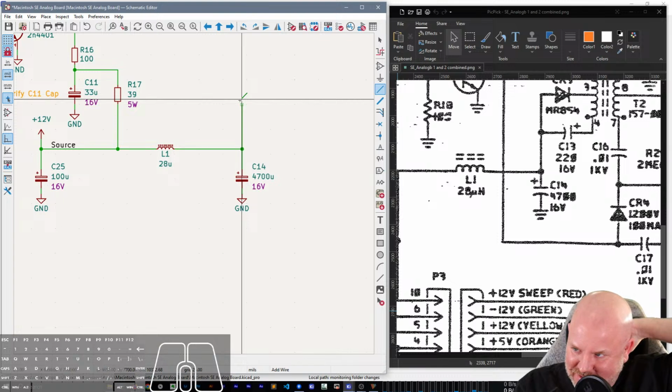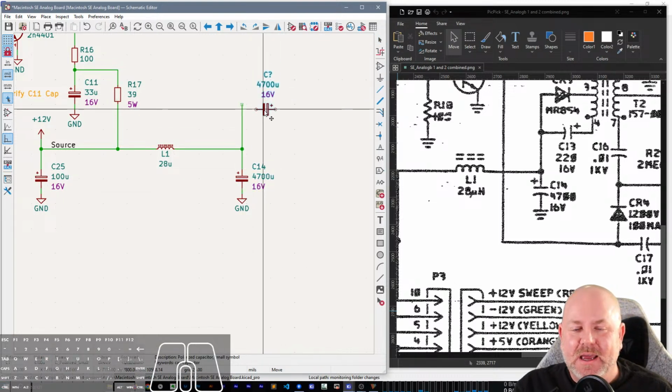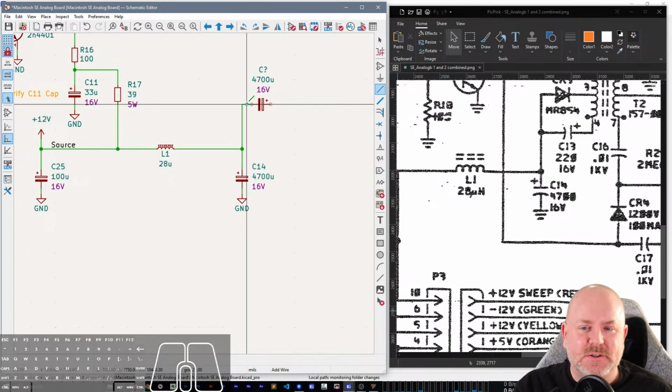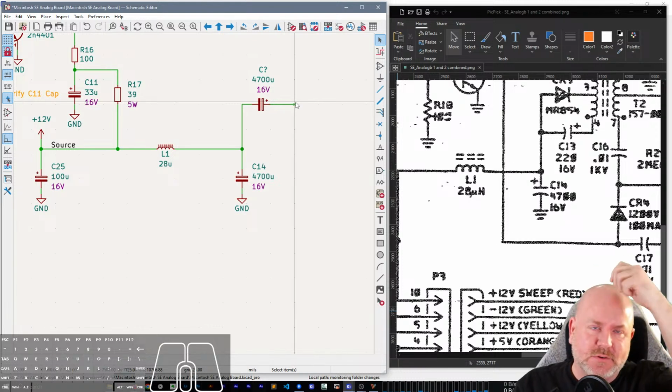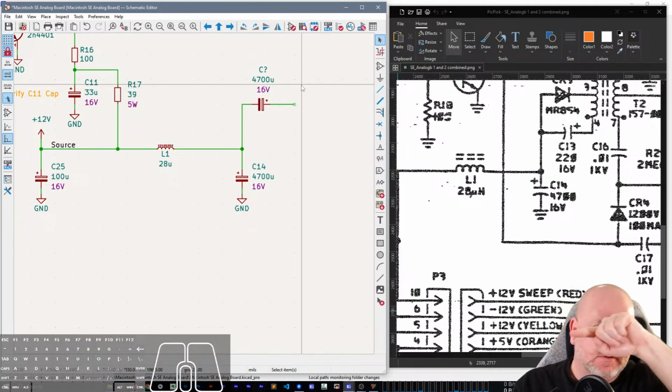All buffers and inverters should have cross-flow pinouts. Oh my God. I think that's actually why I don't like using the 74 244. I can't remember, but I feel like there was a buffer that I was using for a while, and it has a terrible pinout. And I think it's the 244. I use the 245, even though it's really only available in the wider package, even though there is some stock out there of the smaller surface mount package. But other than the enable pin, it's a very clean layout.